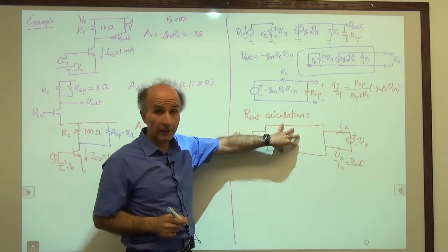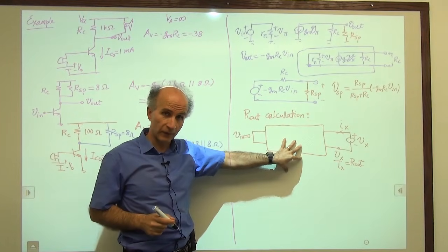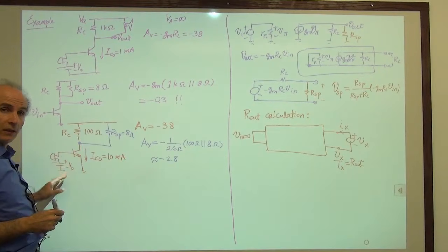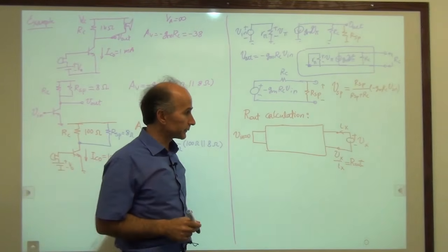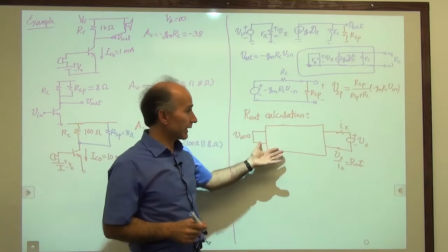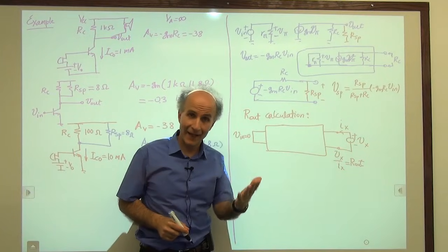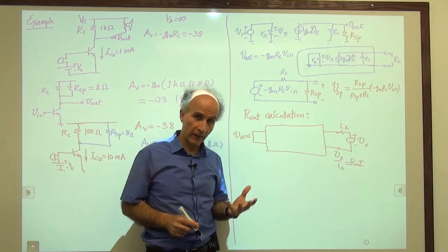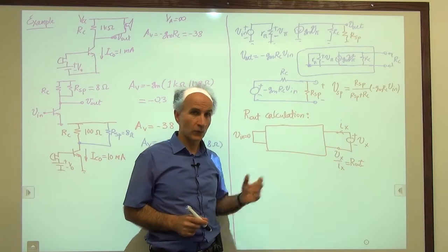So all independent sources, inside, outside, everywhere have to be set to 0, including batteries here, including the input, because the input is independent, and so on. So our out calculation should be quite familiar to you because it's really exactly the same as the Thevenin resistance or Thevenin impedance that we have calculated in basic circuit theory. So it's the same thing.